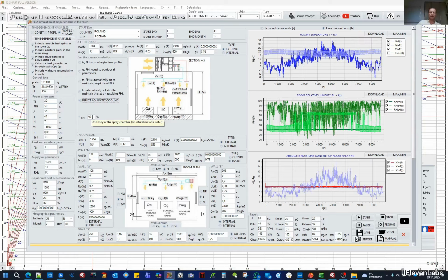So we use water to lower the sensible heat but increase the latent heat, which significantly raises the relative humidity. And here each spray chamber is characterized by a certain specific saturation coefficient. Here we assume about 90%. It might be slightly less, but let's say 90% is a kind of standard. And consequently, for each combination of external air parameters, we will obtain a certain supply air temperature.